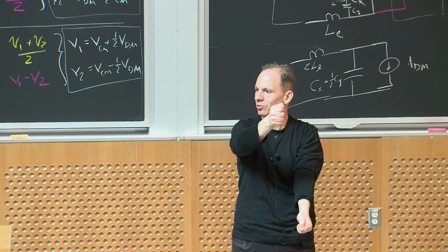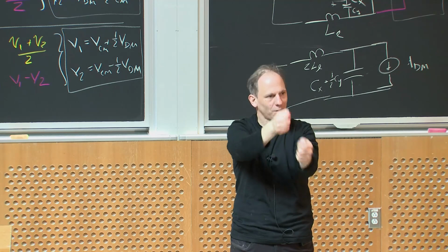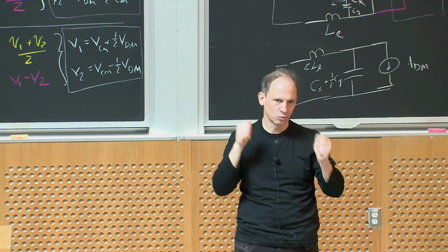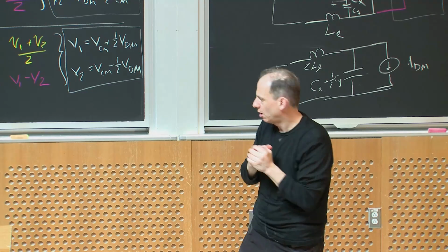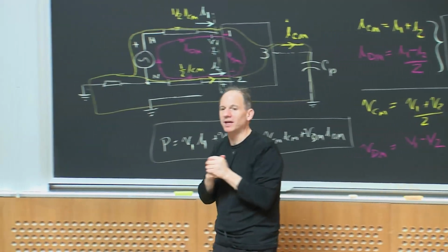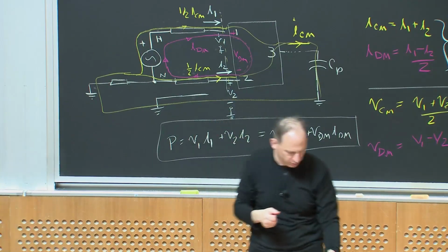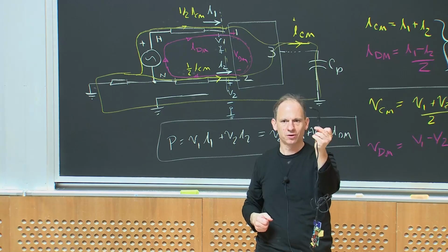So I can use differential probes, or sometimes you look at how much your ground's bouncing and say, yeah, that's related to my common mode. But I'll think differently about how I will deal with those. And even when you're making measurements, you tend to do this. Actually, if you look at this cord, you see this kind of cylinder on this cord?